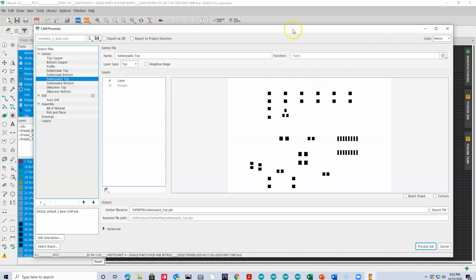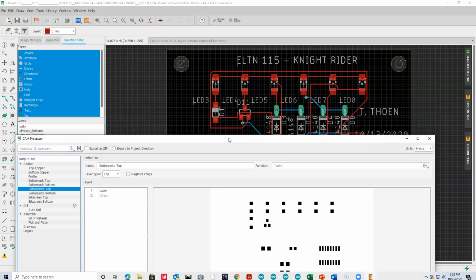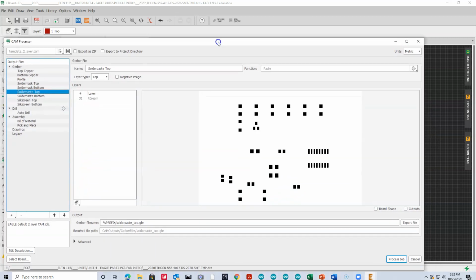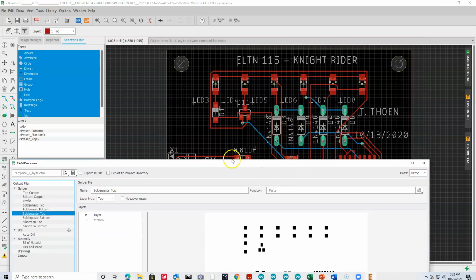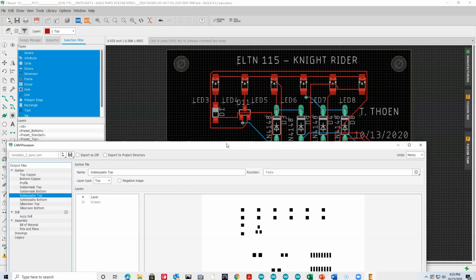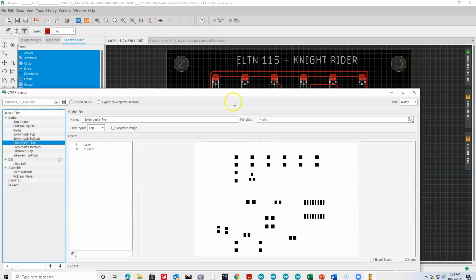And if you look at the board itself, every one of those stencil locations, for example, these pads over here would relate to these pads here. And on the board, before any of the parts are placed on it, this metal screen would go over the board, and they would basically use a silk screening method where they wipe this solder paste onto the board, and then the components are placed on there.